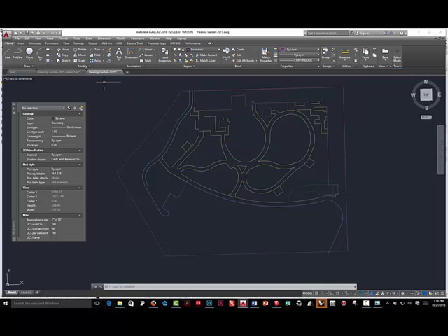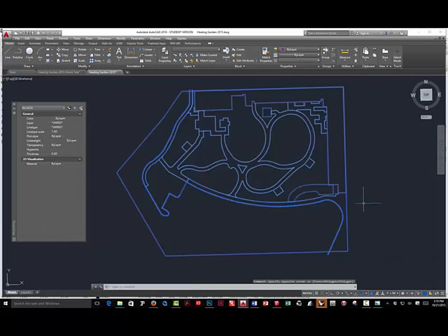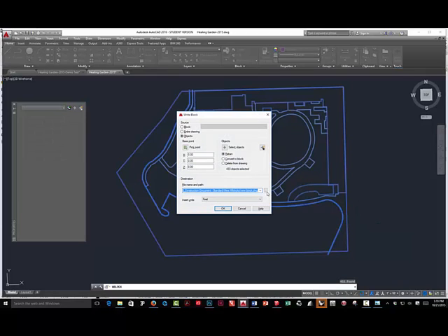And now I'm going to select everything that you can see here, and I'm going to type W block, okay? And that stands for write block. Now what it's really doing is writing out an AutoCAD file. Since I already have objects selected, I don't need to do anything. I don't need a base point. What I do need to do is specify the file path and name.